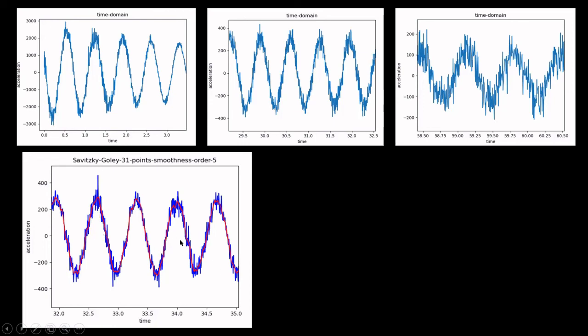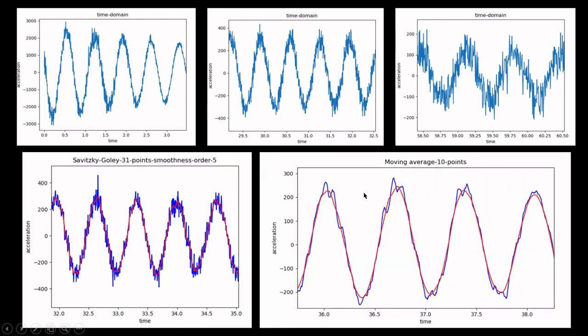Even after doing this, it is not enough. You can also use another filter like a moving average filter to reduce this. But to get the sharpest point, I use multiple filters. After using the Savitzky-Golay filter, on the same data generated, I use the moving average filter. After using the moving average filter, you can see that even at plus minus 200, the signal was appreciably converted to a sharp point.